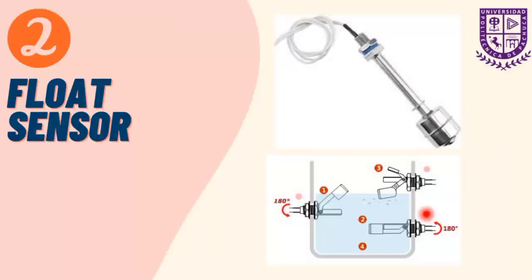The float hangs from the valve, waiting for the water level to rise so that it begins to float on top of it. Once it begins to rise, the valve placed at the other end begins to close on the fill valve tube, and when it reaches the indicated level, the valve closes.